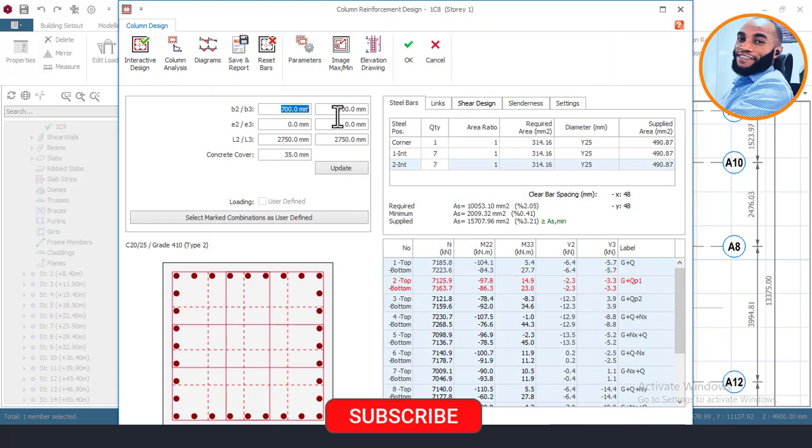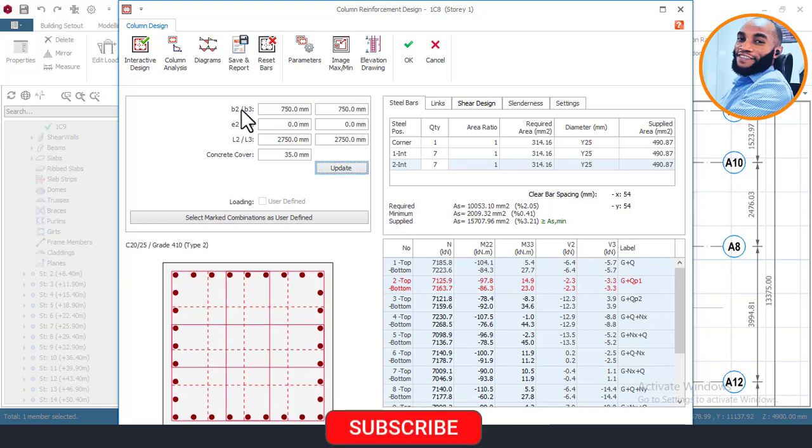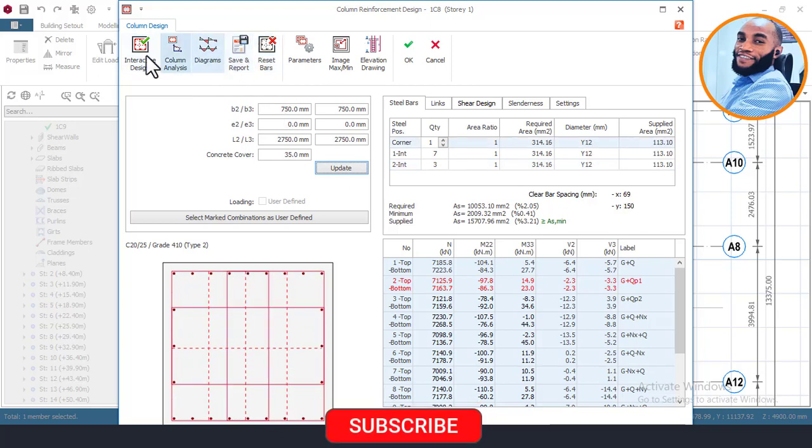Basically it is okay, but I don't want to use a 700 column. I want to use a column width of 750 by 750. I want to use the conventional one, and I'll say update here. So basically 700 was okay to carry the load, but I just want to choose 750 and all that. Okay, so I'll come here right now and say reset bar first, and then come here and design.